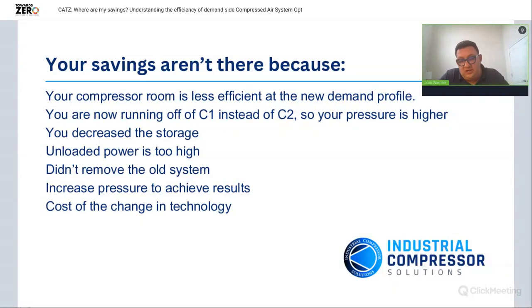You can adjust how many cycles your inlet valves and solenoid valves see. Technicians can be changing out solenoid valves and inlet valves, and depending on who's watching the system, it might be believed that that's an equipment level problem when it's actually a system level problem.